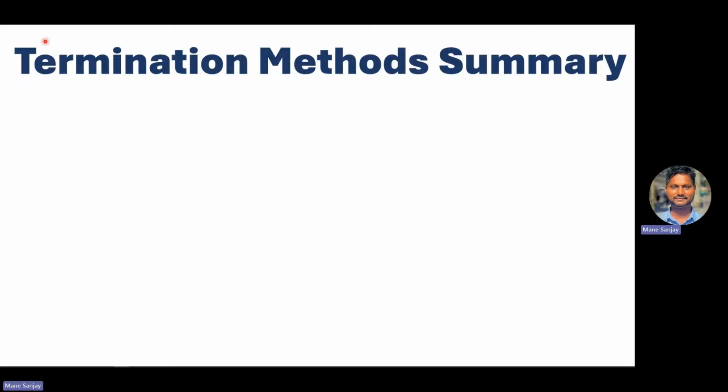In split termination, we use two 60 ohm termination resistors, and on top of that we add the capacitance, and the approximate value for the capacitor is around 4.7 nanofarad, and it depends on the need of the filtering effect in the network. You need to vary that value of the capacitance.